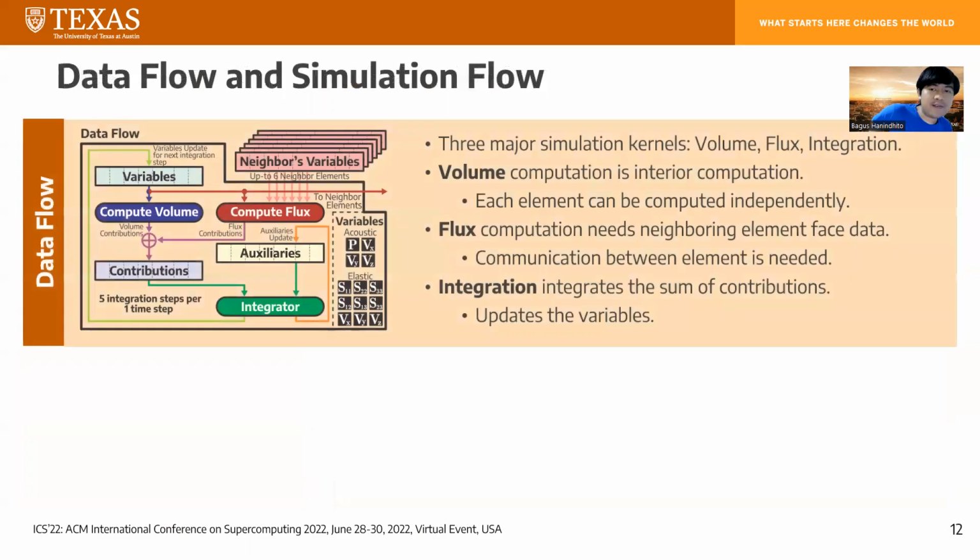For the data flow itself, there are three major simulation kernels: volume, flux, and integration. Volume computation is completely interior computation. Each element can be computed independently, while the flux computation needs neighboring element face data. So there is some communication between the elements before flux can be computed. The last is the integration, which is a very small kernel.